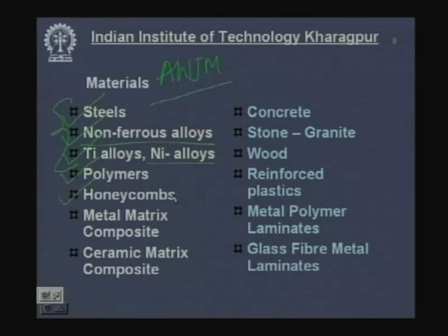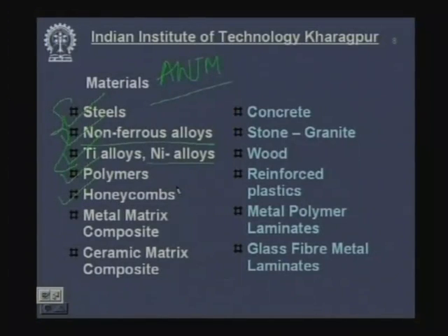They are very difficult to machine because the whole system distorts, but they can be machined. Metal matrix composites and ceramic matrix composites are newer developments, possibly developed in the last 10-20 years, and they can be very efficiently machined. Now, the other end of the spectrum is water jet machining. Water jet machining cannot be used for machining these; abrasive water jet machining is required.